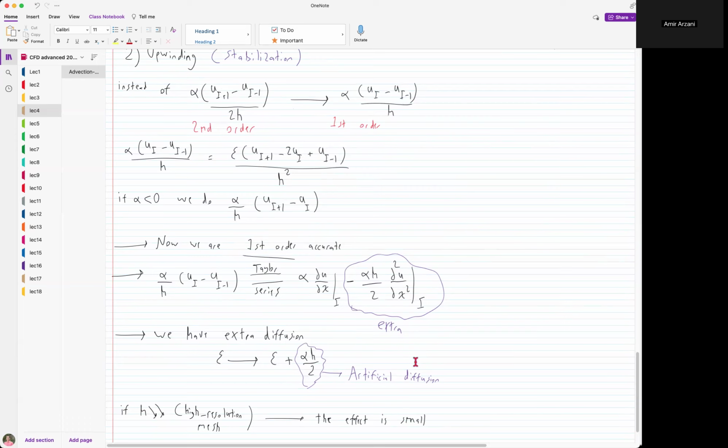You can see how to prove that with an appropriate choice of that free parameter, which turns out to be a function of the grid Peclet number, you can make this numerical discretization exact. Even though you have artificial diffusion, you're scaling it in a smart way such that you get exact and correct solutions.